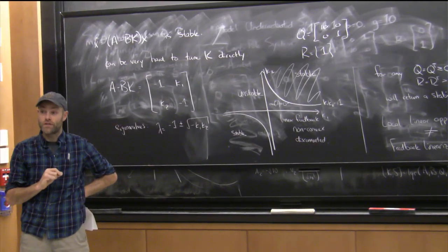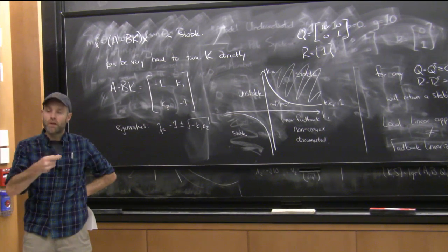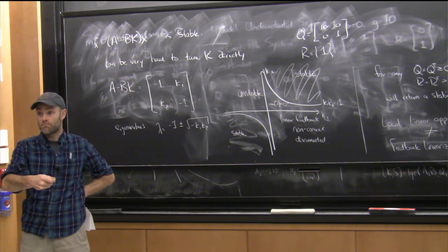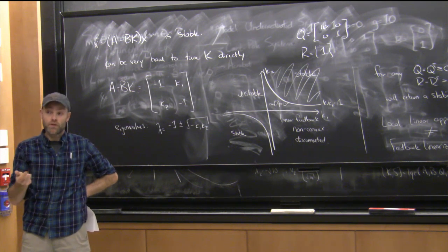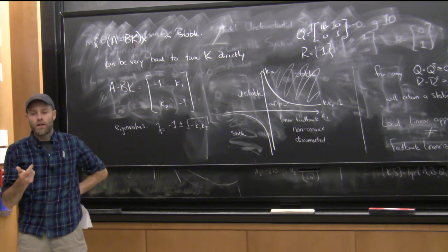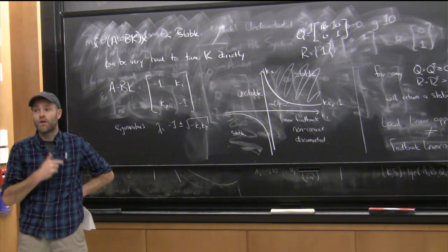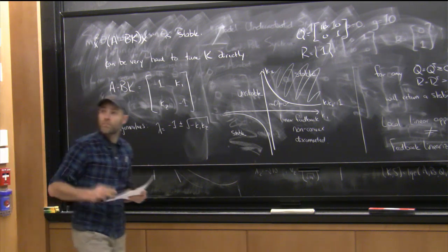The optimal control conditions come out of dynamic programming. Value iteration is the numerical algorithm we use to do dynamic programming on a discrete approximation. In particular, I tend to use value iteration for the infinite horizon case. And then LQR is an analytical solution to dynamic programming that works if you have linear systems. Yeah, it's great.